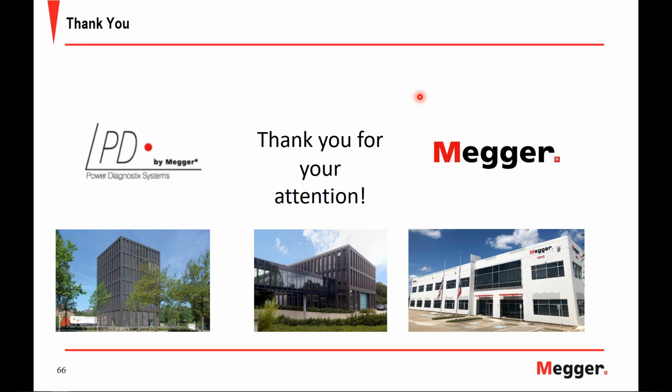All right, thank you. Huron, as online is with 80 pF and offline with 1000 pF couplers, can we compare these two? Well, the 80 picofarad online couplers are referring, I guess, to the coupling capacitors from our colleagues from Iris Power. They have these 80 picofarad EMC couplers, which are designed as a first order filter, looking at the 80 picofarad of the capacitor and the 50 ohm impedance of the cable.